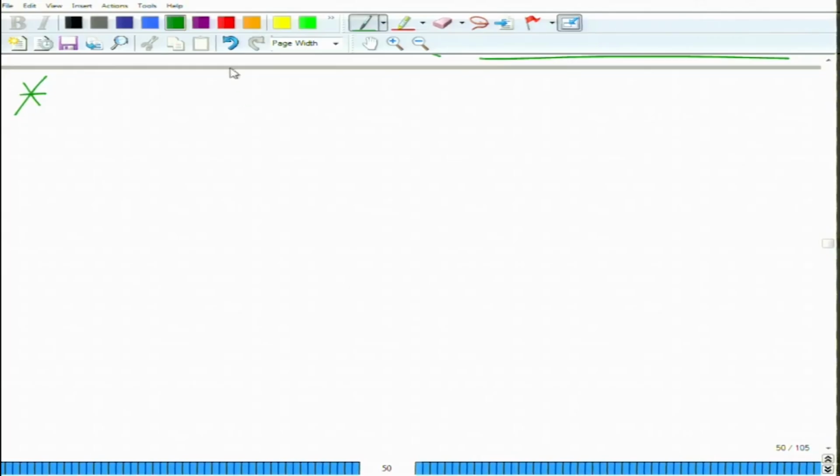So, we are looking at sampling, and in particular we are looking at impulse train sampling to convert a continuous time analog signal to a discrete time signal, where we are multiplying the signal x(t) by an impulse train. We have also derived an expression for the spectrum of the sampled signal in terms of the spectrum of the original signal. And what we have seen is the following thing. So, what we are doing is we are discussing sampling